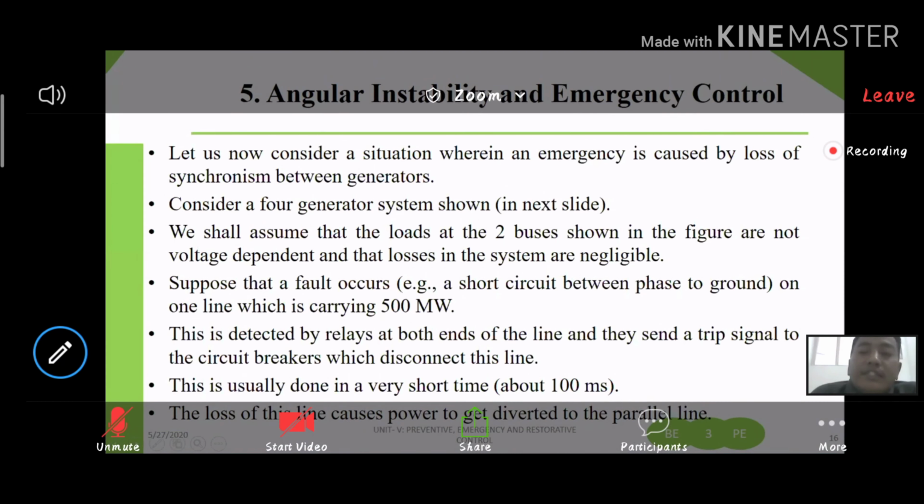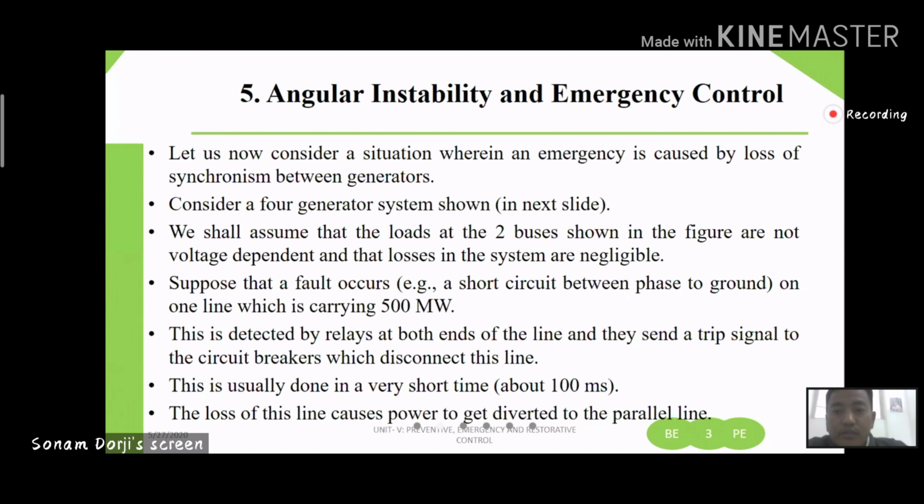The emergency control. Okay, so last class we learned about the emergency control, how to carry it out, and when we have to carry it out. The first case, yesterday's lecture, was when equipment limits are violated. For example, we considered the thermal limit. If it exceeds 1500 megawatt, then a blackout may happen. In such a case, we learned how to carry out the emergency control.